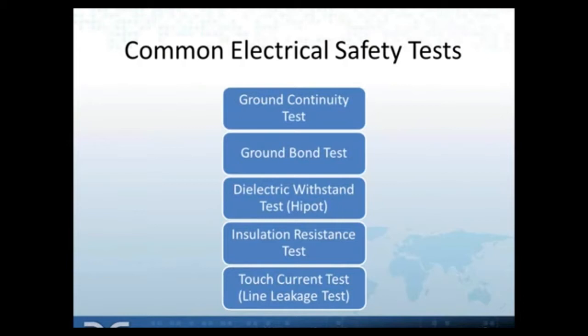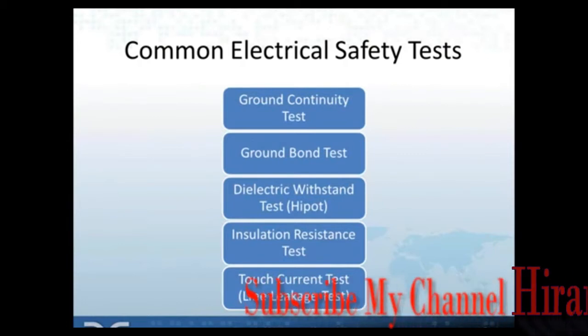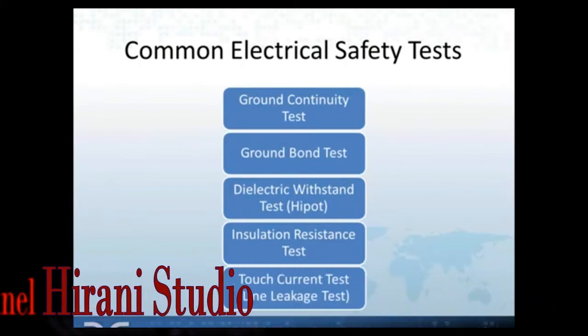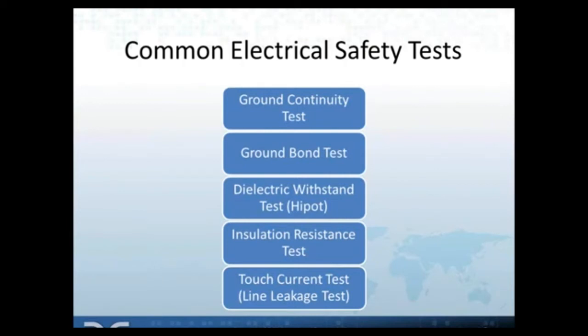Most injuries and electrocutions are caused by either electrical products with faulty insulation or a product with a defeated safety grounding system. The insulation in question is used to separate the power line circuit from low voltage circuits, isolated power supplies, the chassis, or the case of the product.